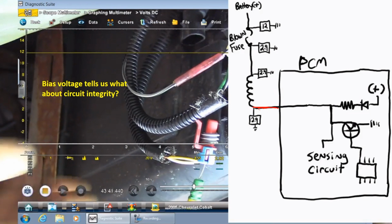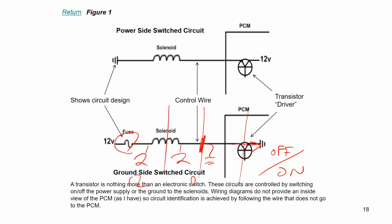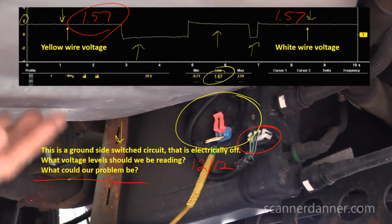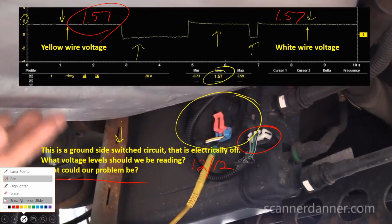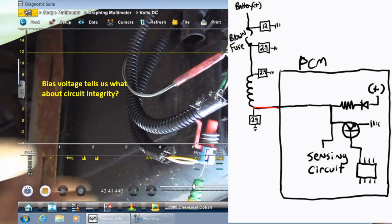It doesn't. So it's just an initial test. If I want to check to see if that circuit can handle current, then maybe in my scenario up here when I saw this 2.9 volts and I realized that my voltage is a little low, so maybe we could argue my ground wasn't quite as good as I thought it was. But once I know which one my control wire is, I would just simply unplug this.